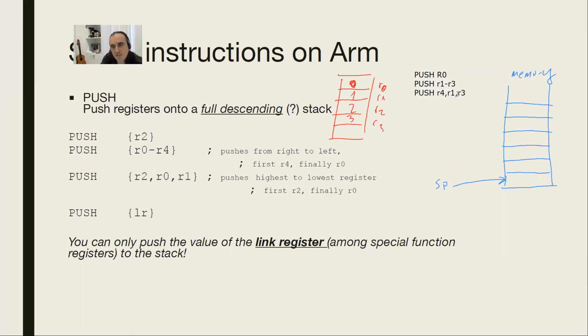So what happens, guys? Let's see. This is the first line of code, and it's going to be writing the value inside R0 to where the stack pointer shows. Very simple, right? So I'm going to be writing 0 here. What happens also is the stack pointer now starts to point to the next location. So now the stack pointer is pointing to here. Everything clear?